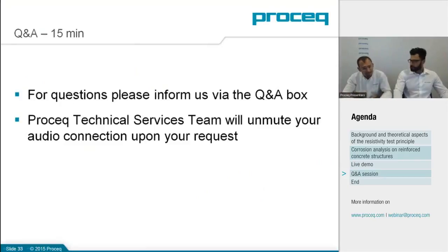This might become useful when dealing with highly carbonated concretes. Without going into detail, carbonation increases resistivity, and so the fact that you might observe a decrease in resistivity with a broader spacing might give you an idea of the carbonation being there.